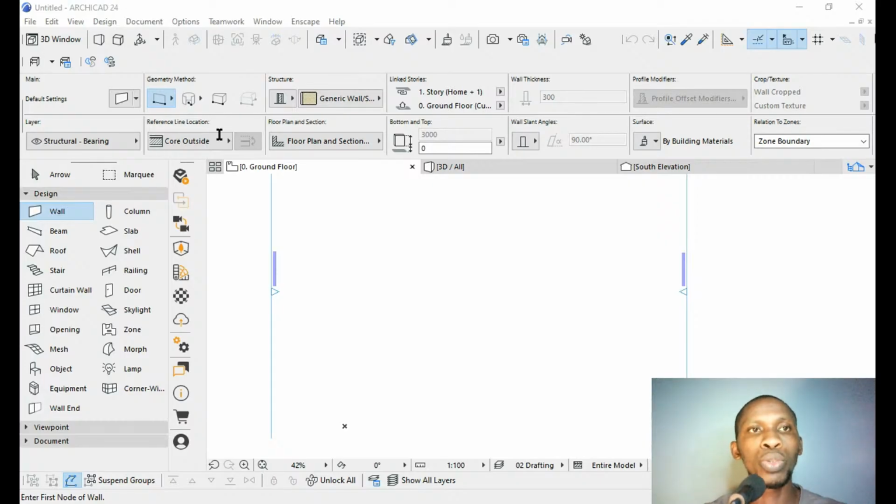So it means I want to now add. The default wall height is 3,000. Then I now add 300 on top of it, right? But what I usually do most times is make use of not linked, and then I change it to 3,300 as the wall height. So from ground level is 0.